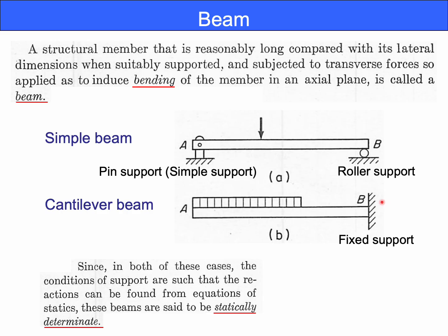The fixed support generates three unknown reaction components, two forces, Rx, Ry, and the one restricting bending moment. Determining three external reactions using the overall equilibrium equations is the first necessary calculation phase. Considering these boundary conditions, we have to determine the reaction forces, right?